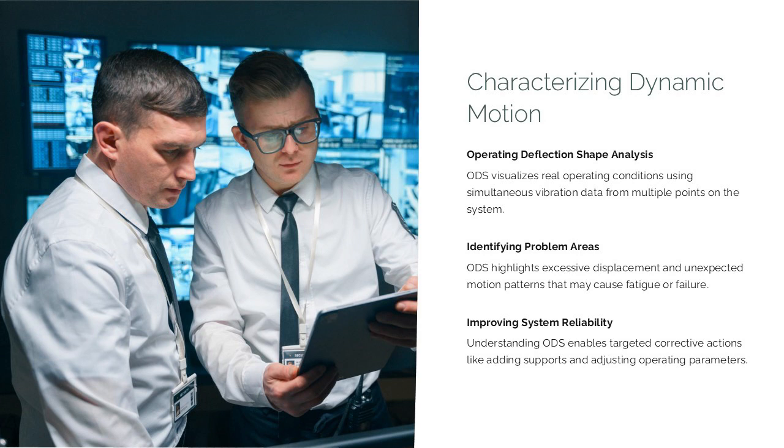Operating deflection shape, ODS, analysis is a powerful tool for visualizing the dynamic motion of a system under actual operating conditions. Unlike modal analysis, which uses controlled excitation, ODS relies on simultaneous vibration measurements at multiple points during steady-state operation. These measurements provide amplitude and phase information relative to a fixed reference, enabling engineers to construct a clear picture of how the system moves at specific frequencies.